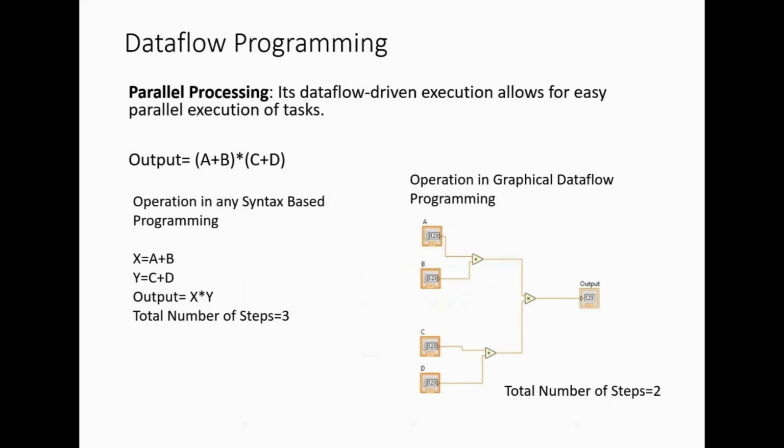Next point is the data flow programming model. Text-based programming usually follows different rules for execution of the code, either left to right syntax or right to left syntax. But LabVIEW follows the data flow programming model. Data flow means any particular function or block will be executed when all the inputs are available, right? So suppose we are going to solve this equation.